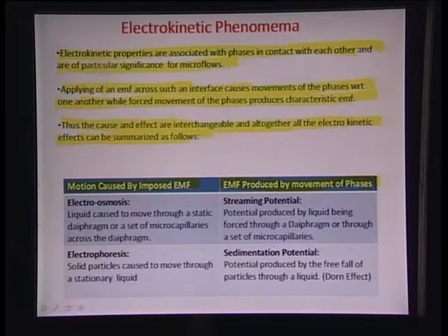Okay. The first category, as we know already, has phenomena like electroosmosis and electrophoresis, where motion is caused by an applied EMF. Electroosmosis is where liquid is caused to move through a static diaphragm containing a set of microcapillaries, or in any case through a microcapillary in general, by applying an induced EMF. Okay. Electrophoresis, on the other hand, is where solid particles are caused to move through a stationary liquid by applying an external electric field.